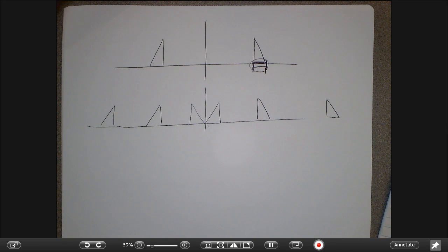The idea should be that as long as I'm taking, on average, enough samples per interval, and that number of samples is above what the Nyquist rate tells me, I should be able to reconstruct the signal even if those samples are not uniformly spaced. And in fact, that's true, but it's a real pain to actually make it work, right?